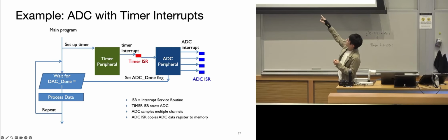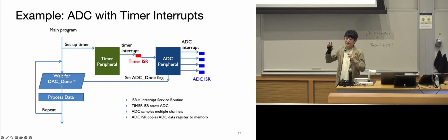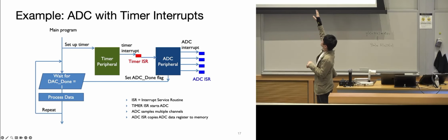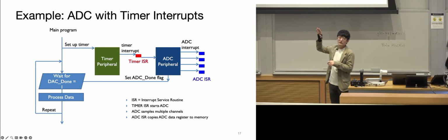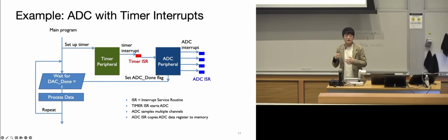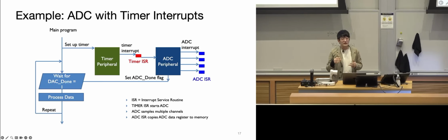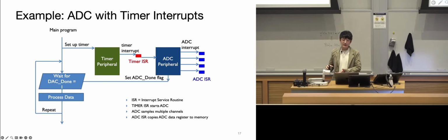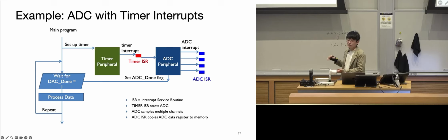The ADC is initialized and sends back a flag saying I'm working on it, and then goes back to the main program. It lets each ADC channel do the interrupt. Remember, each of these external ADCs has its own internal interrupts that can be triggered whenever a value comes in.